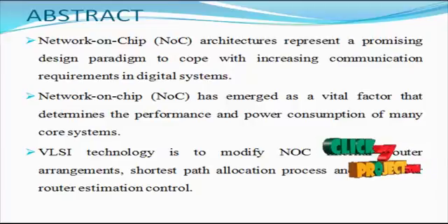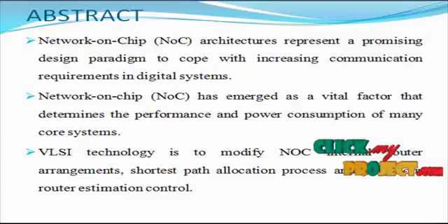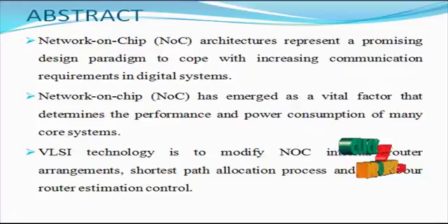Due to 3D NoC manufacturing technology limits and design complexity constraints, current 3D NoC research focuses on simple 3D mesh topology. Ideal analysis shows that the 3D mesh XY is a deadlock-free algorithm that achieves better system performance under medium-size interconnect and typical traffic patterns, but in a larger system with increasing cores and various specific applications, the traditional 3D mesh framework leads to extra delay and reduced performance.